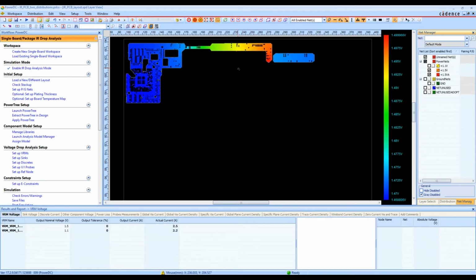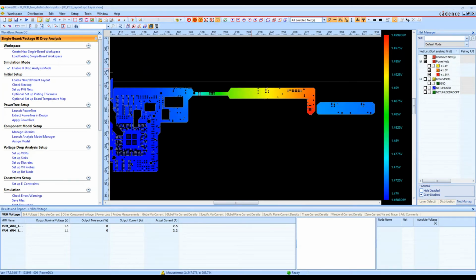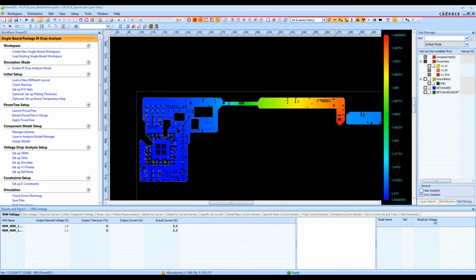And you can see the voltage dropping from the VRM supply right here, where it's the highest and closest to 1.5 volts, till it gets down over here to our sync device, where it looks like we've lost about 30 millivolts from our supply to our sync. Where are we losing most of that? You can see pretty quickly from this graph that most of it is lost in this little finger channel, and actually quite a bit here.